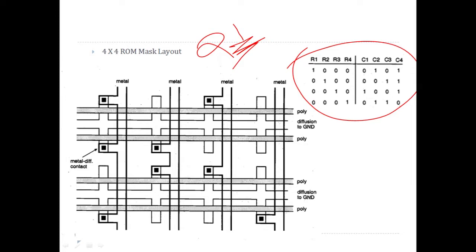So it's very obvious looking at this. Let's consider any row for that matter. Let's assume R4. In R4 you can see this is nothing but the polysilicon layer. These are diffusion layers 1, 2, 3, 4, where there is a cross of diffusion layer over the polysilicon, a transistor is formed. Now because these are 4 transistors, the drains are here. This is drain, this is drain, this is drain, this is drain of R4. The sources: this is source, this is source, this is source, this is source. This source is shared with R3. These are sources of R3, and these are sources of R4, and they are shorted together, and from their common connection there is another diffusion layer which ultimately connects to the ground.